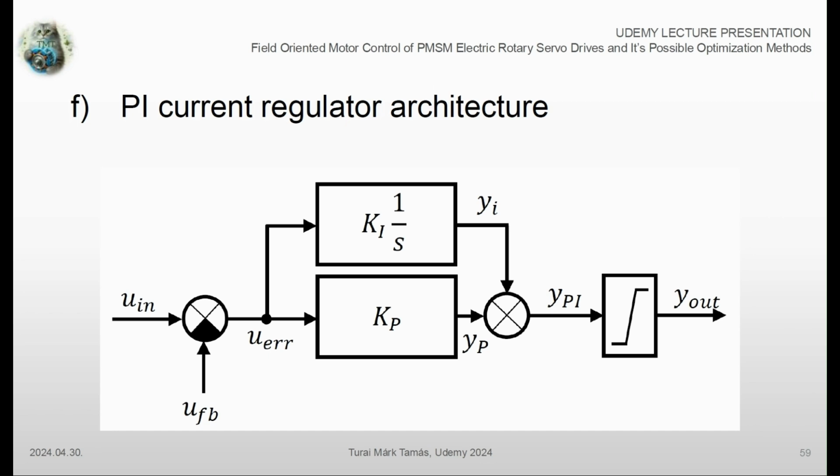Finally, I have brought an example of a common regulator block diagram representation that shall look very similar in case of a MATLAB Simulink implementation. As we know, the input of the regulator is some kind of an error signal, which is interpreted as the difference of the reference and control signals. Afterwards, this error signal is multiplied by the proportional gain directly, which is added to the output of the integrator. The output of the PI controller is the sum of the proportional and integral gain operations together.